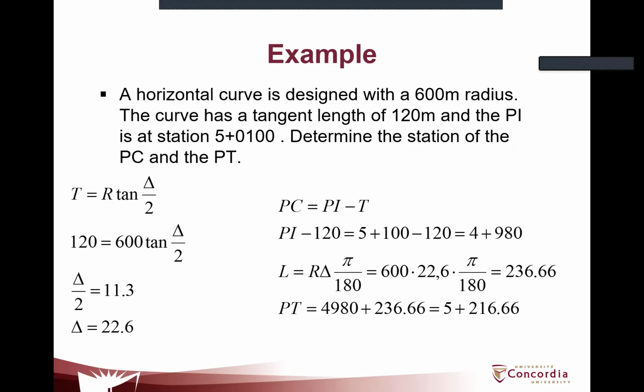That will add or subtract from the PI the tangent to determine the PC, but to go from PC to PT will add the length of the curve itself.